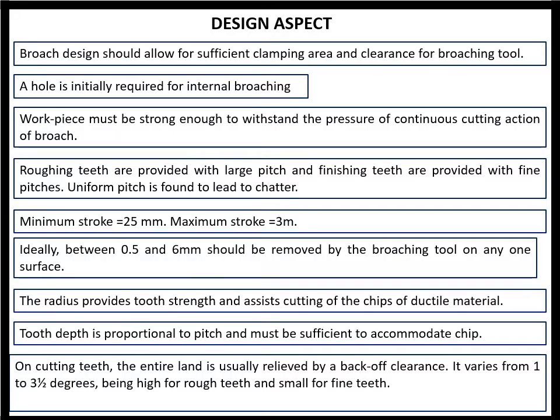Now, what are the several designing aspects for the broach? A typical broach should be designed with a sufficient rear end and a front end for clamping purposes. That is first and foremost important.